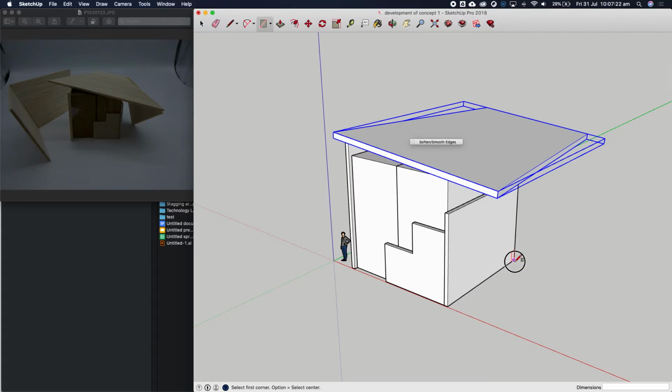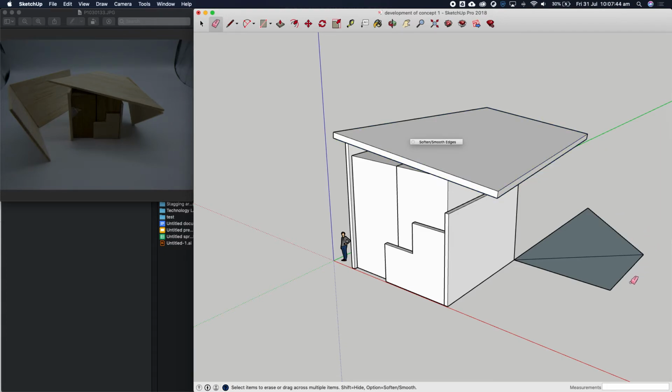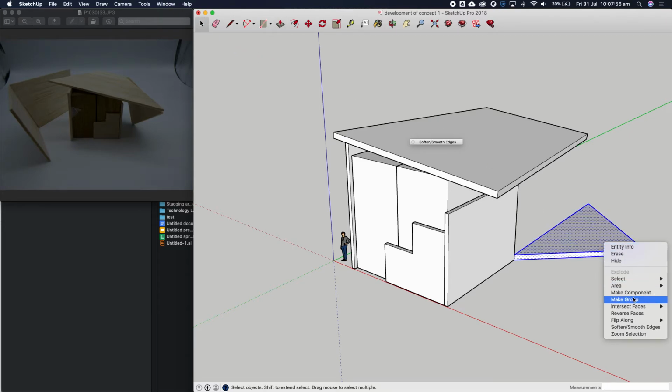We go over here, we draw our basic shape. We use a pen tool to make our triangle. I'm assuming the triangle is a normal triangle kind of thing. Remember, I'm doing all this with arbitrary values. I'm not really punching in anything unless it's an extrusion. Then I go to the push-pull tool, bring this up by 300. That is my side pit done. Triple click on it, right click, I'm going to make it as a group.